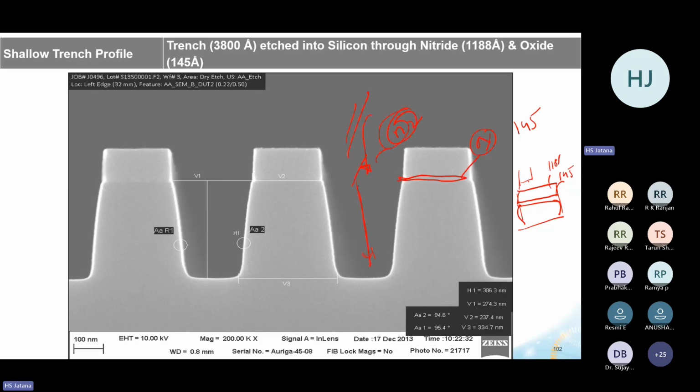So there will be three different types of etching continuously, and there will be an etch stop. You have to decide the etch stop here, because there are two mechanisms of etch stop: based on time, or based on the etching process seeing a different layer. But here it's not seeing a different layer; it's silicon, and below also is silicon. So I have to decide how the etching will stop when a particular dimension has been achieved and a particular angle has been achieved.